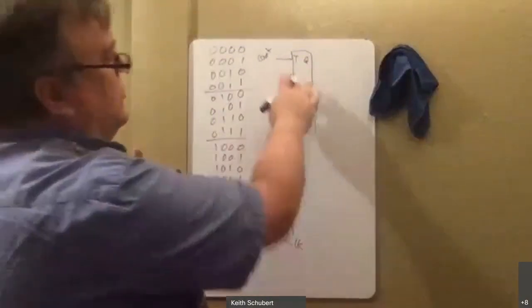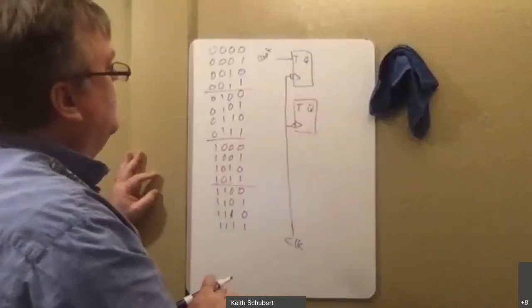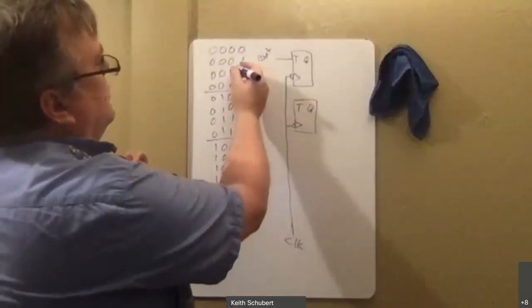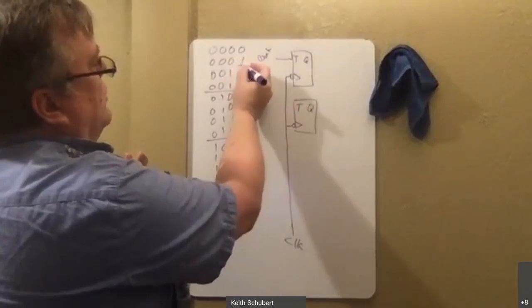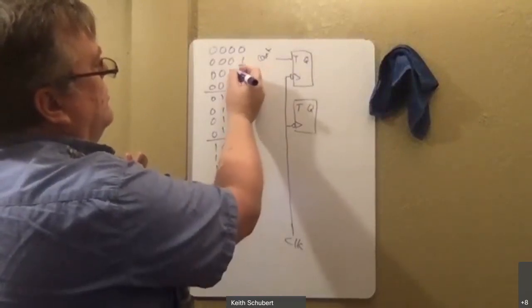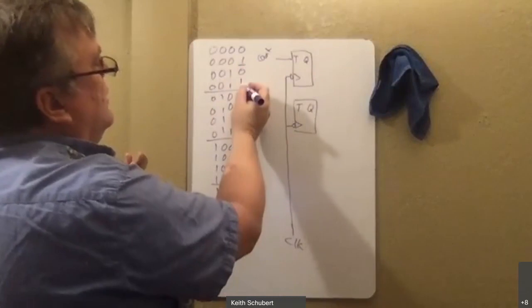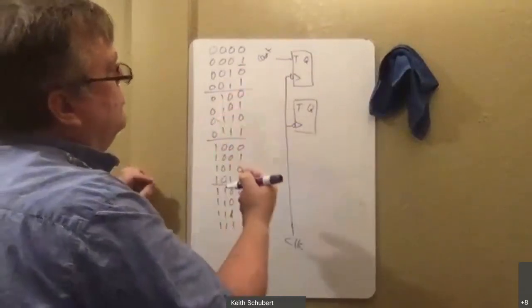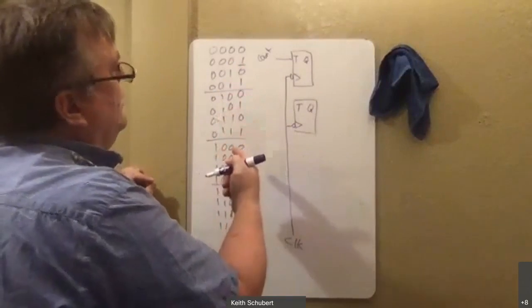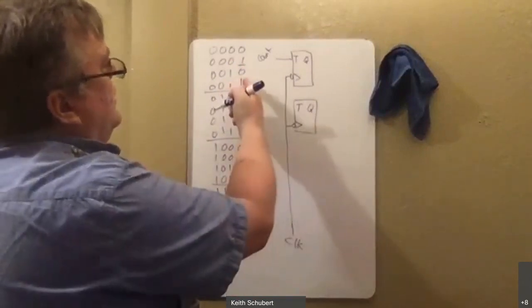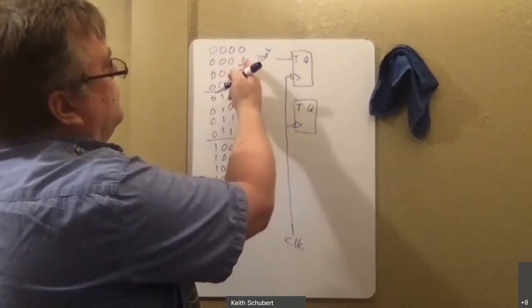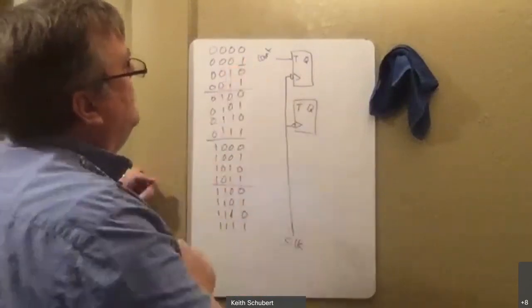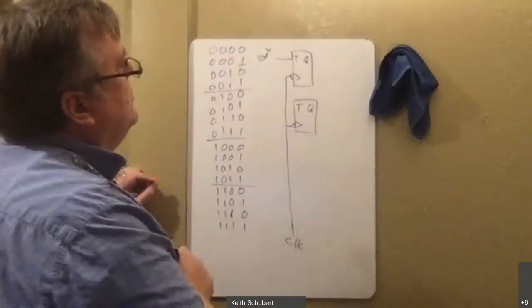Right, so I know it's synchronous because each of these are hooked to the same clock. I only want to do the count transition whenever it goes 1 to 0. Right? So that means I'm only going to look for a count pulse, right? When both of these, right? When this one is a 1 and becomes a 0.